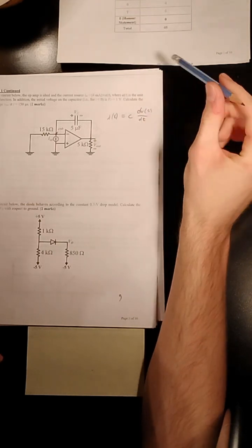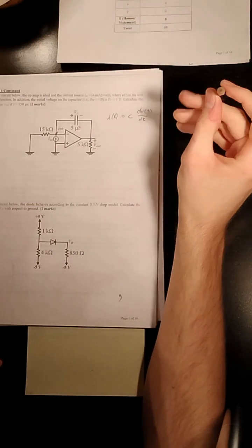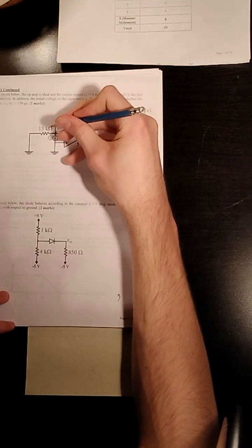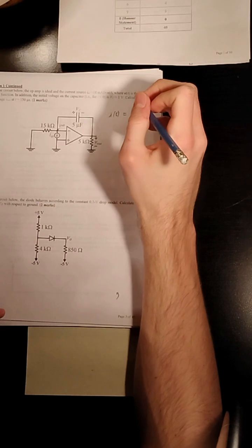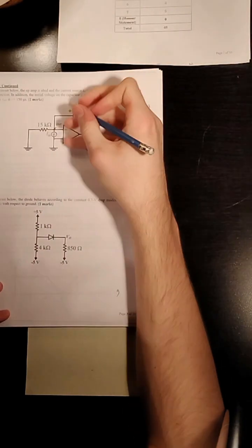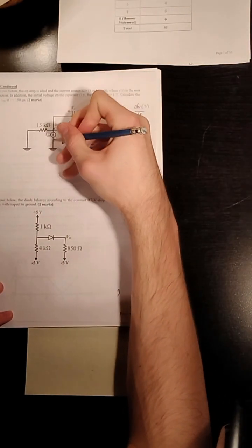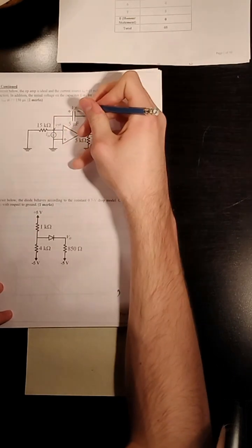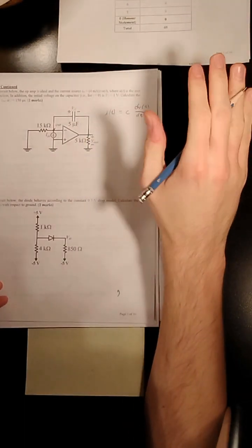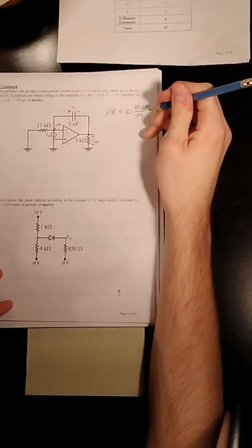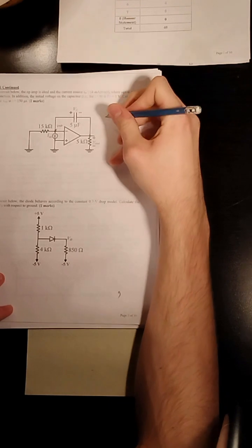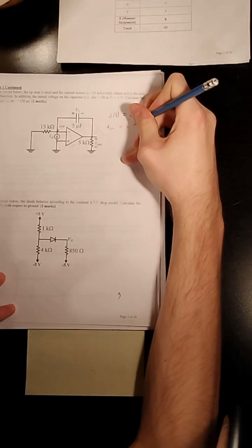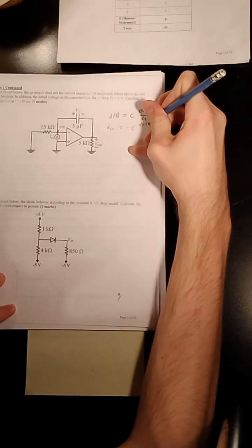My argument would be that as you steal current from the positive end of the capacitor, your voltage across the capacitor is going to go into negative territory, right? As you steal a bunch of positive charges, this is going to get more negatively charged. And so your VC is actually going to go negative. So it starts at 1 and goes down from there. So I might say that I in is equal to negative C dV of t by dt.